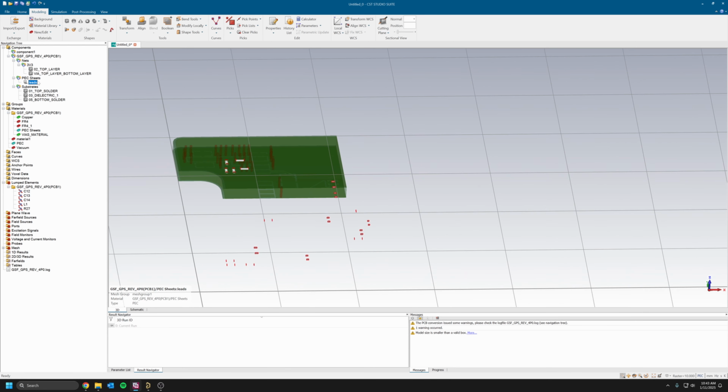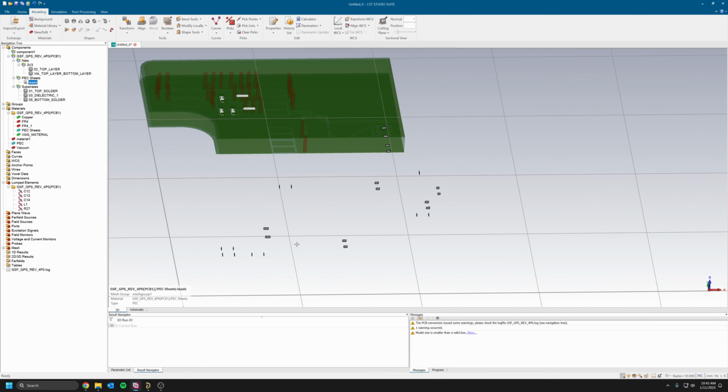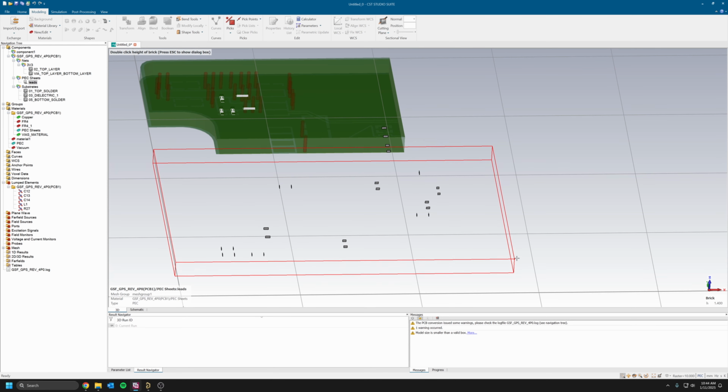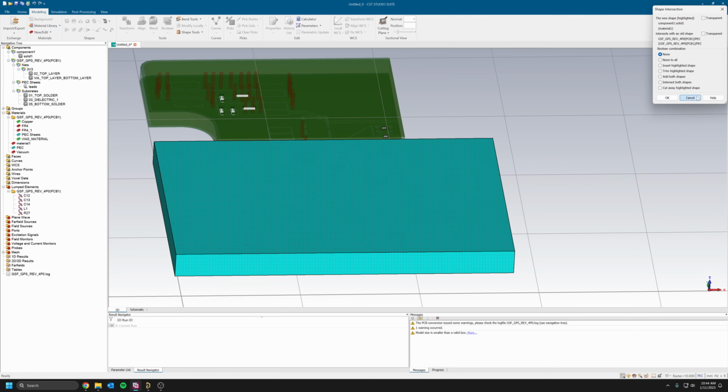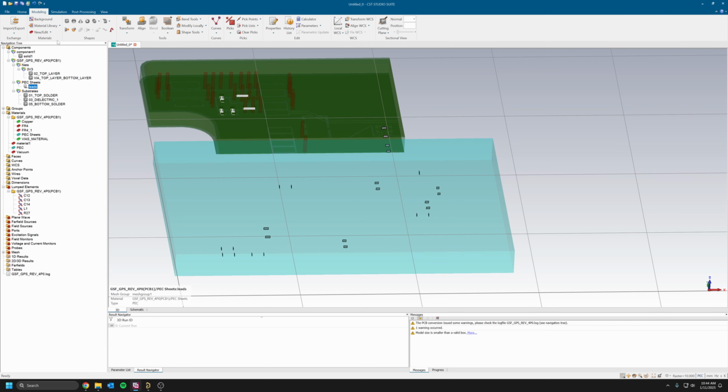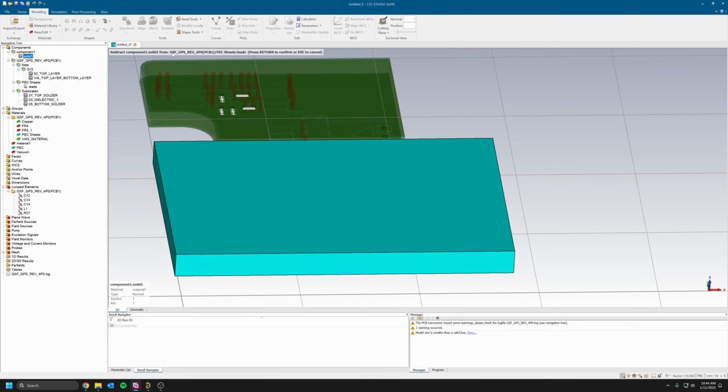So we could have selected leads as well, which are perfect electrical conductor sheets, and those are used to connect the ports of the components. So we don't need these, especially those that are outside of the region of simulation. So we're just going to select these again, do this same procedure, cancel, and then leads, Boolean, subtract, and then solid, enter.